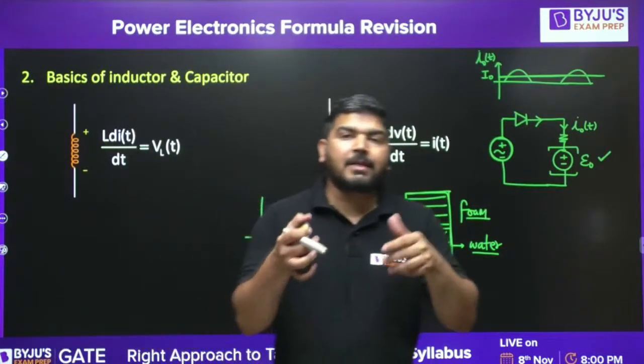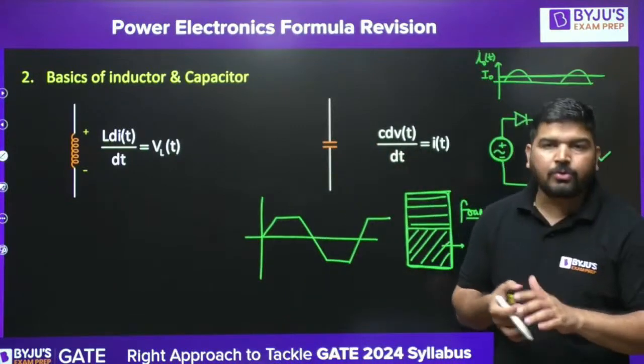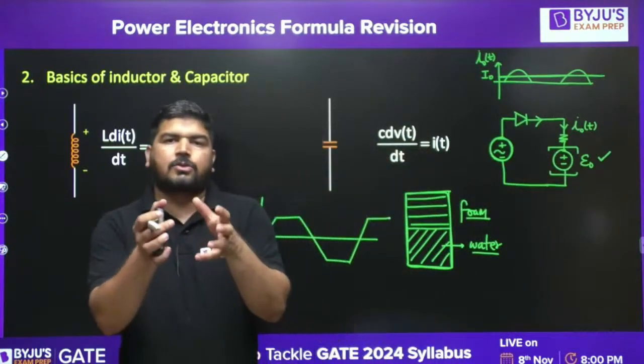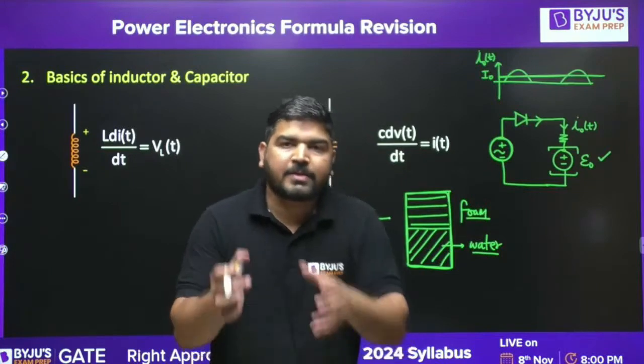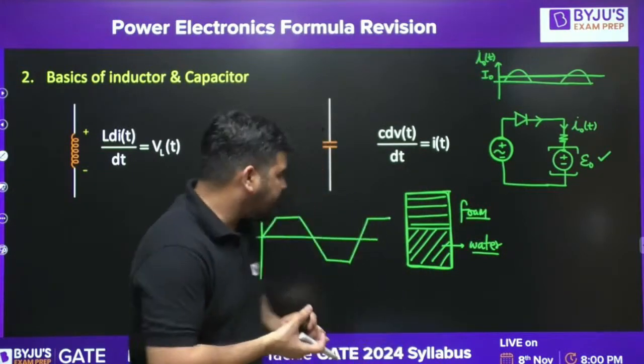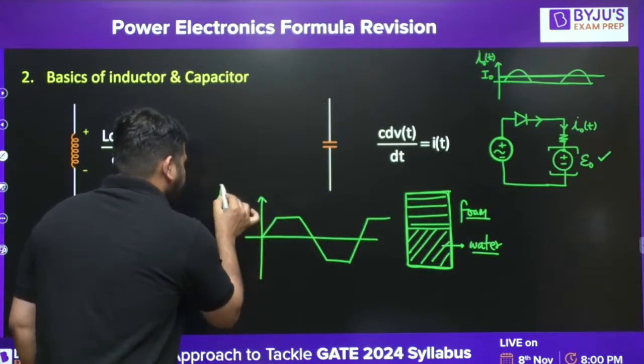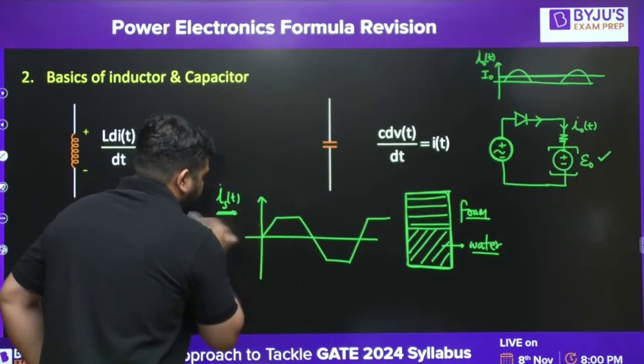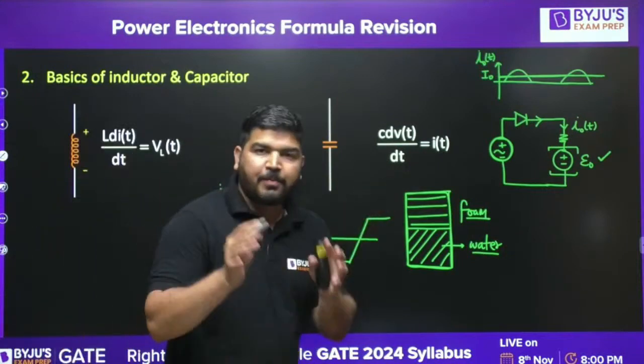Those harmonics represent the distortion. So what I want to do is calculate the distortion part. I want to separate out that distortion part. How to do that? It's very simple. Let's say this is the current signal, IST. In that current signal, we have a pure sine component.